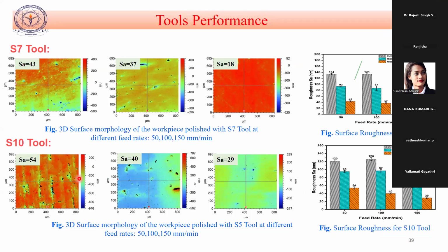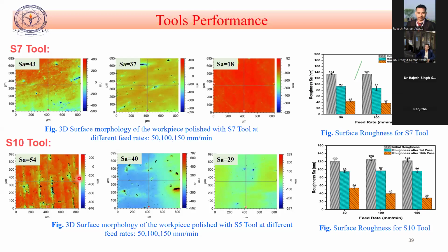When removing material at micro-nano scale, as I have shown in the previous micro milling slides, the effect of plowing comes into the picture. This plowing word we never hear during any machining research. So in micro scale, this plowing is coming and the burr is forming. If we are removing in nano scale, then obviously the plowing will be more significant.